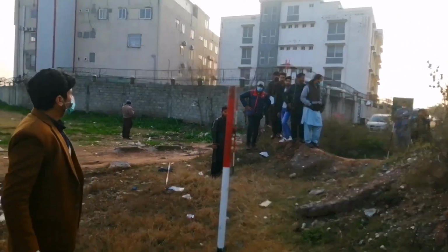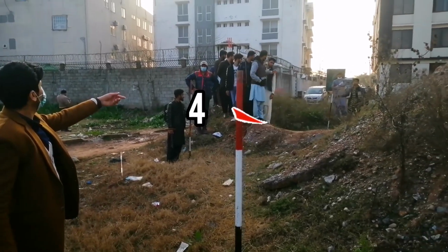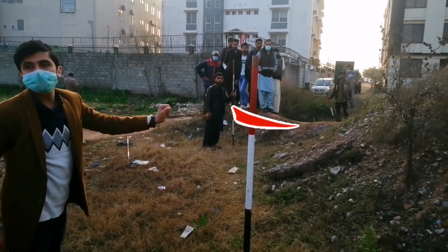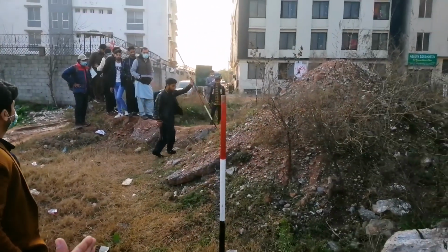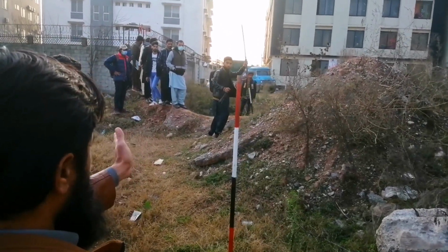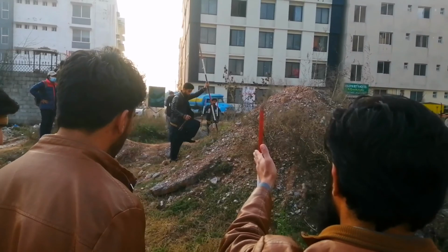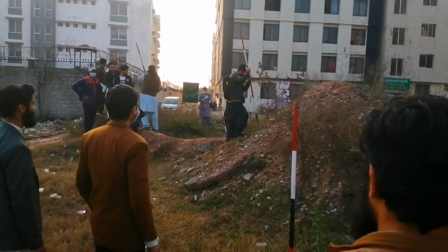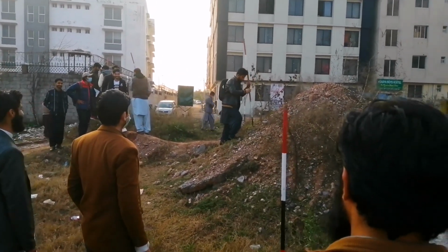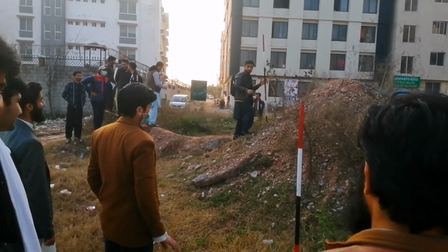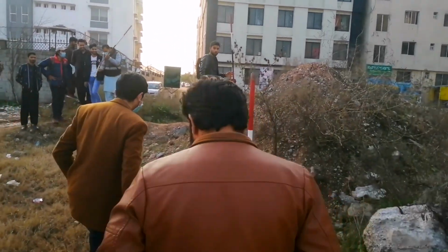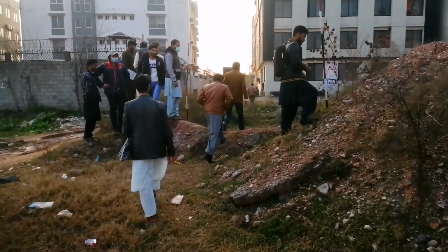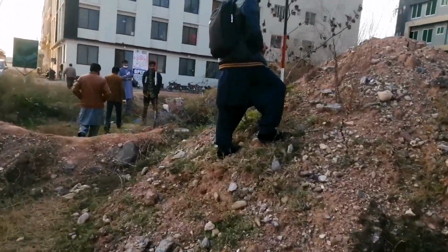and ask the surveyor standing at the point 4 to move in a straight line with these 2 points. So now he is guiding that student to come over there so that the point 2, 3 dash and this new point are aligned. So he's guiding the surveyor to move in a straight line with all those previous points. So as long as it is aligned, he will ask that surveyor to fix that rod there. In the same way, all the points are ranged with respect to the previous points by shifting the stations and aligning all the previous points, and we will continue to do that until all these points are in line with each other.